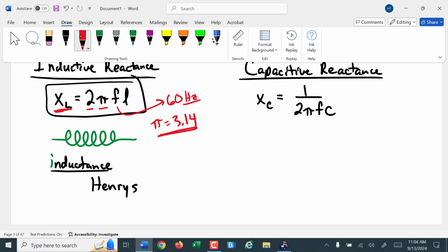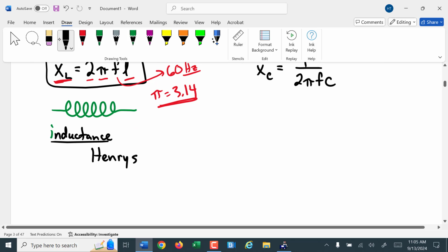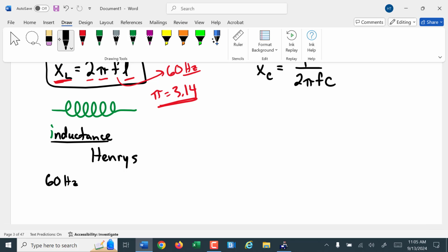And this is something to be careful of. I've seen European machinery shipped over. Got to be aware of the possible difference in frequency. L then is the inductance in henries. So if we have, well, let's do 60 hertz and 50 millihenry circuit. Find the inductance, or the inductive reactance, I should say.